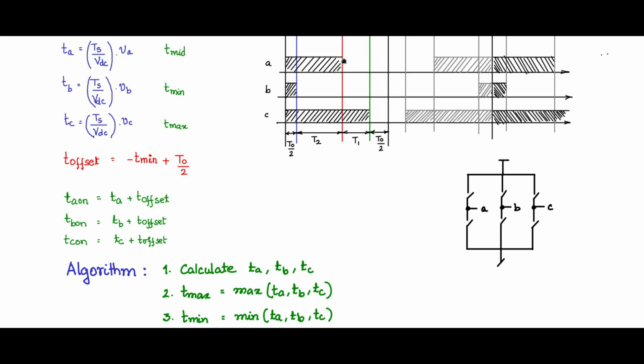So you invert, and when that goes high, delay it and make it high, so that the rise time and fall time will pass, and there will not be a direct shoot through period where a huge current can flow. So this is what is called the dead time inclusion when, in a real circuit, you are giving these signals to complementary switches.